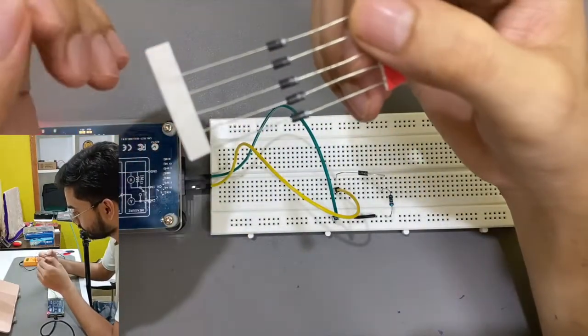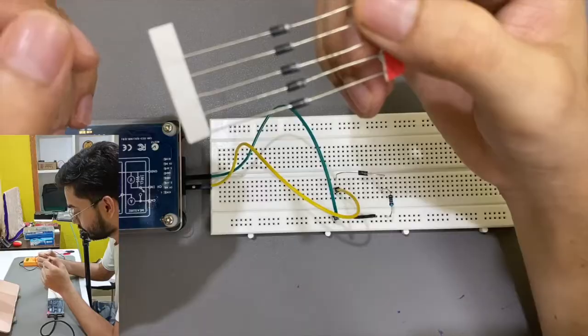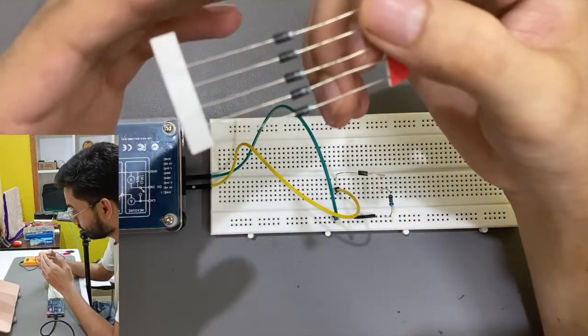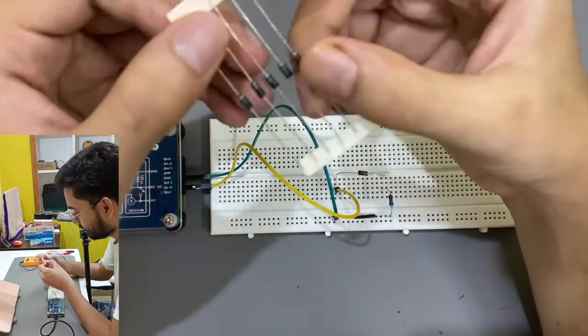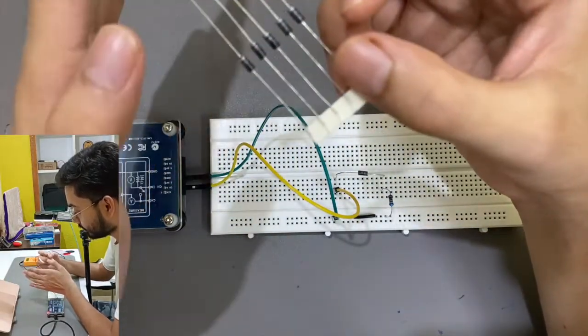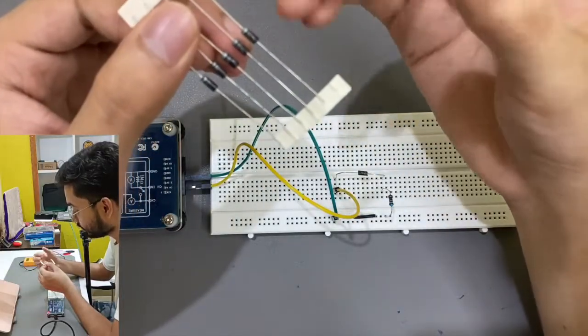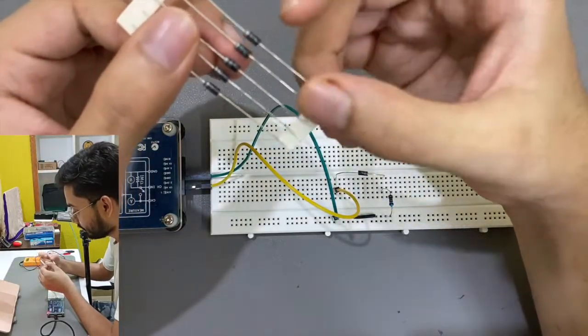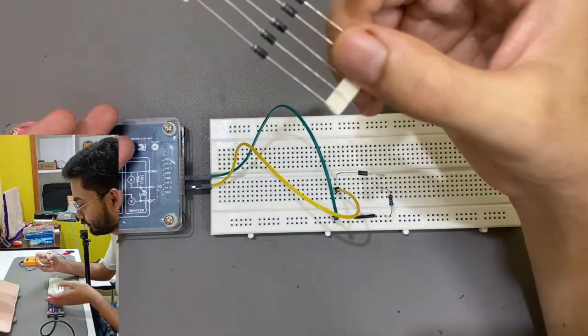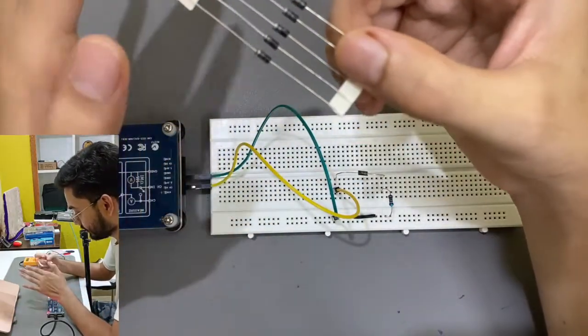If the value of the external voltage source is less than the barrier voltage or voltage drop, then even in forward bias condition the diode will not allow current to flow through it. If we reverse this diode, meaning the negative pin is now connected to the positive of the voltage source and the positive pin is connected to the negative of the voltage source, then this condition is known as reverse bias. In reverse bias condition, there is no current flow through the diode. If we apply any value of voltage through the external voltage source, there will be no current flow through the diode in a reverse bias condition.